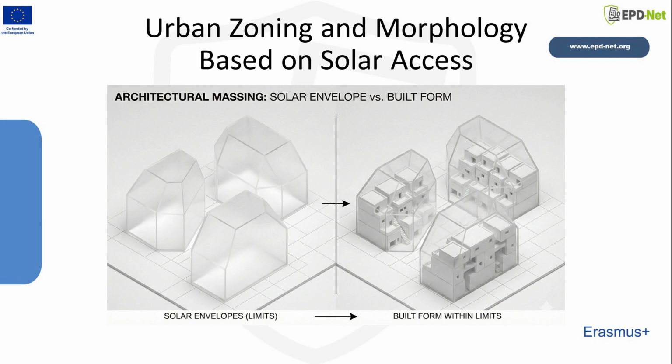Spanish Grid, downtown Los Angeles, high density. A project on the diagonal Spanish Grid achieved high densities, 80 to 100 DU/AC, while ensuring 4 hours of winter sunshine and 8 hours of summer sunshine. The resulting solar envelopes appeared crystal-like, and the resulting designs were typically consistently higher on the south side than on the north. The resulting spaces were light-filled, allowing for distance views and the free flow of air through the city.